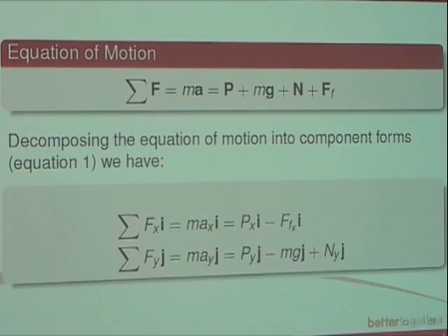So that's why, although in the vector equation you add all the forces together because it's the sum of all the forces, these are vectors, okay? So obviously that's one vector and the opposite vector is in the other direction, but they're all still positive. But because we've decomposed it, we need to make sure that we've got our signs correct. So anything that's running in the same direction as x, okay, is positive, and anything that's in the opposite direction is negative, okay? So you've got Ffx, minus Ffx there, okay?